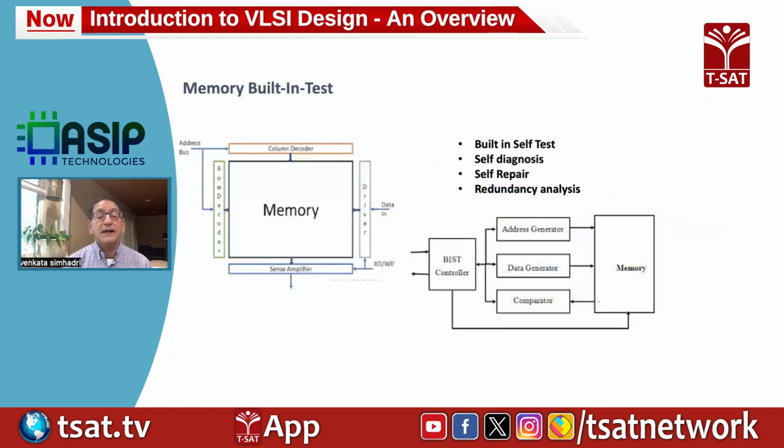Similarly, if you have a memory block in your design, let's say a 1 megabit SRAM block, and if one memory cell is not functioning, then you can't throw away the whole chip. So people came up with a methodology to add some redundant cells in that memory block.